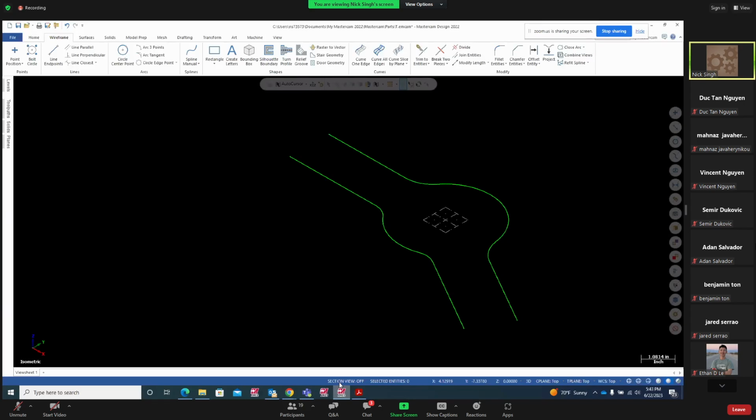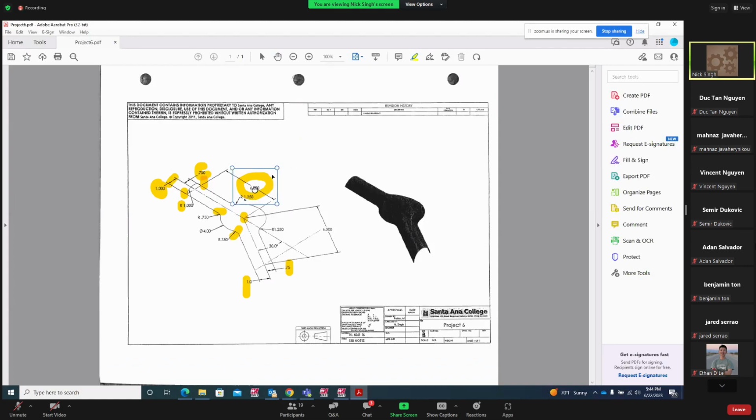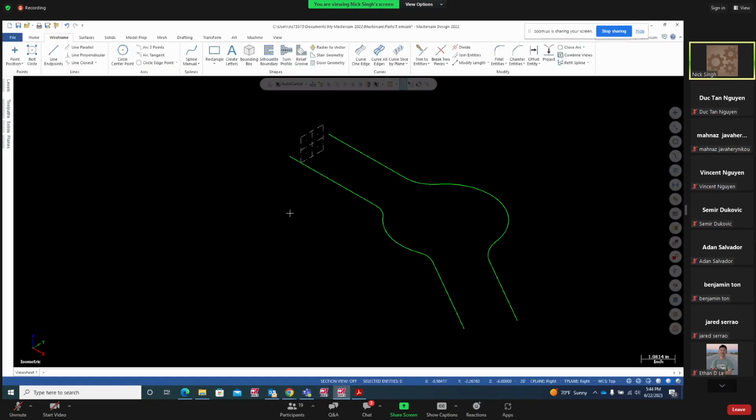So go to construction plane right, change to 2D. I'll go to construction plane right and click on Z. If you do, it says select point of new construction depth. Look at the Z minus 6 inches. And you can see that on the blueprint also, it's minus 6 inches right there. So Z minus 6. That's where we're going to create that arc with the radius 1 inch. All right, so we are good.